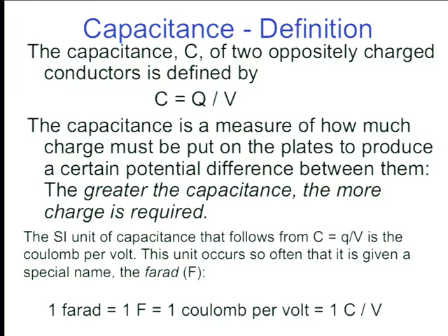The current goes through the resistor. I might put an ammeter in this circuit here, and I could put a voltmeter across here to measure the voltage on this capacitor. The current will flow, but eventually this will charge up, and once this is the same as this, the voltage around the circuit is 0, and this current will stop. There'll be no current anymore.